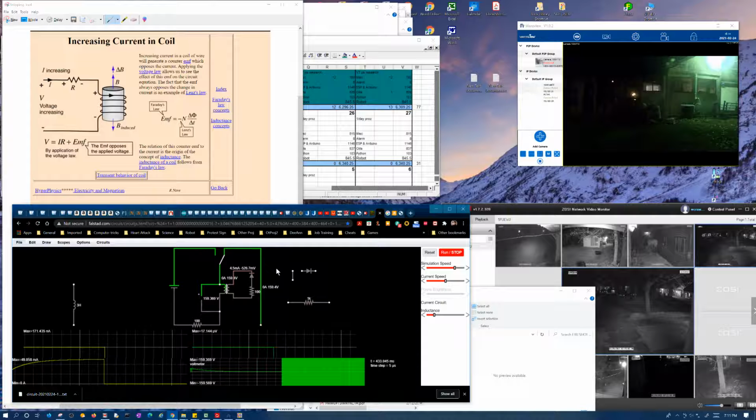But setting that aside for a moment, just because it's got 10 times the number of windings, that right there means there's 10 times the ampere turns. So if you're dealing with 50 milliamps to charge it, that's your charging current, it should be 10% of that on the discharge path under those conditions, because you've got 10 times the windings.